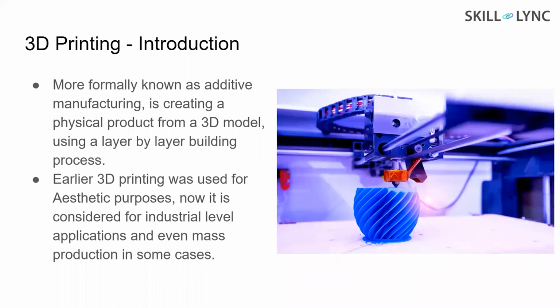So if you want to manufacture a plastic component, you first need to design that component, and after that you have a lot of things, like your injection molding machine. In the molding machine you have your core and cavity, and your ejector pins. As an engineer, when you design this plastic part, you also need to design all of these things to make it manufacturable. So just to show or manufacture one single piece, it is much more useful to use this 3D printing technique rather than the conventional methods, right?